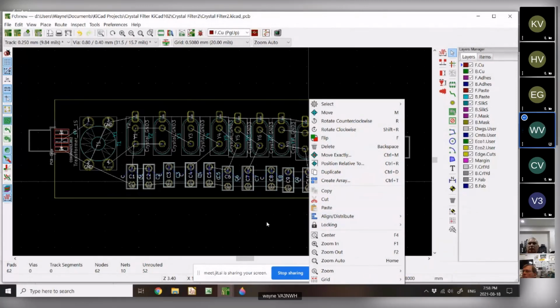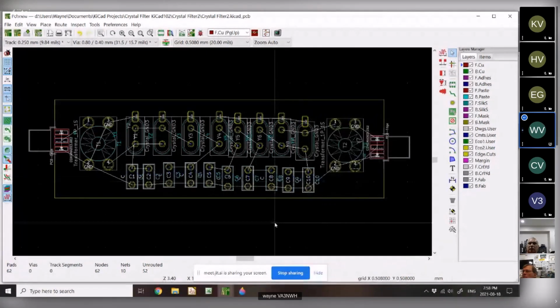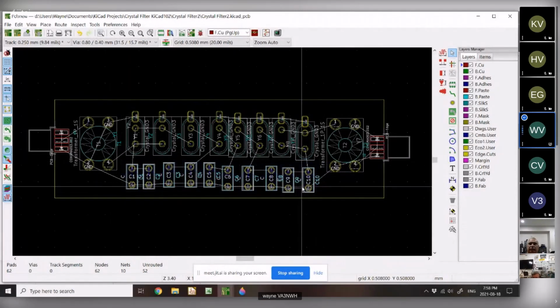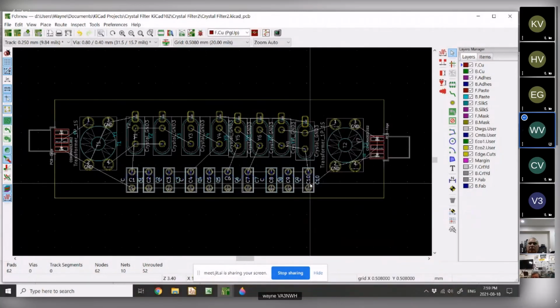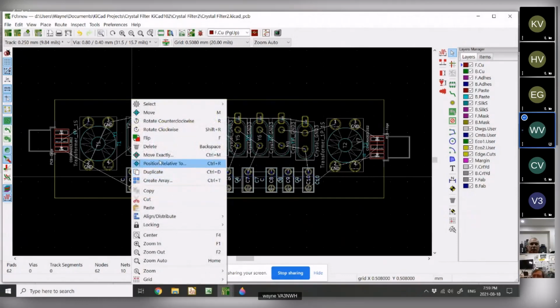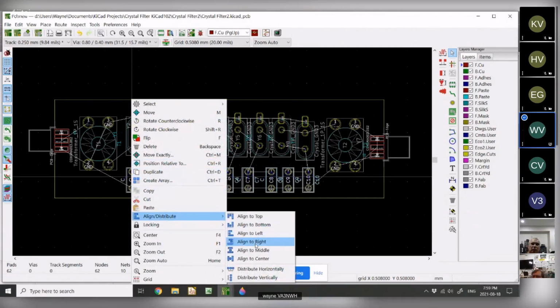Actually, let me take this off here. I'm going to say I'm satisfied with the distance between the left and right on these things. I could line them up a bit better, so I'll go with that. If they're okay lined up left to right, what I really need to do to align and distribute is I need to align to the top or bottom first, and that's what you get. So you get a nice little set of them. They're all the same height, but they're still not evenly spaced, so you do the align a second time. And to do that, you distribute horizontally.